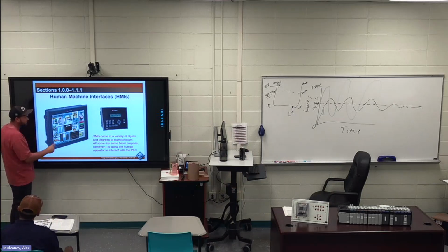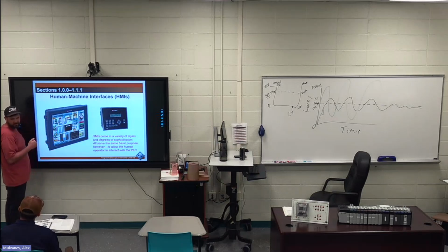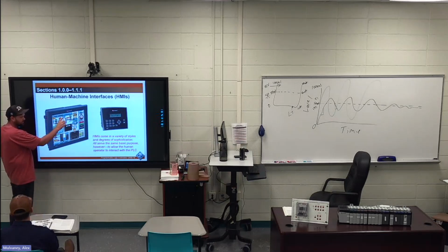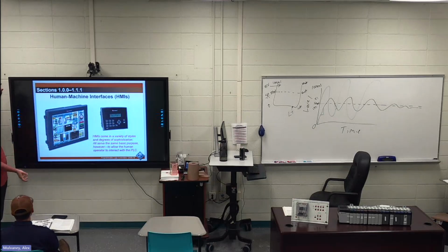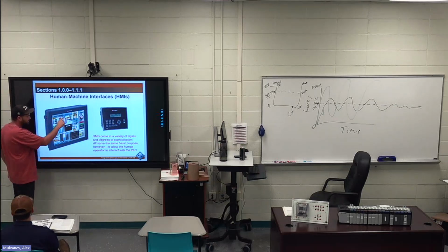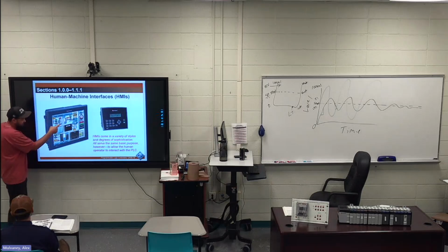If you can see that tank up at the top, you can see a level on that side. That level is just an animation that you pull from the program and put right there. Then you pull from the analog input for the detector on that tank and link it to that image. Does that make sense? So you would have an analog image connected to an analog input on your PLC, which might be a differential pressure transmitter on the side of the tank. And then you link it to this. And then you can say this is some type of mixing thing.